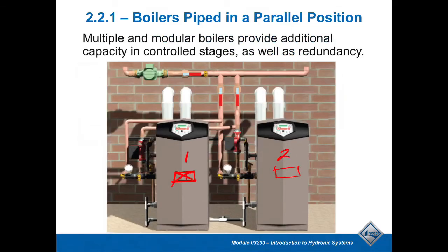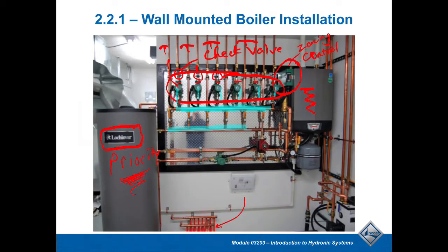So this would most likely be my inlet temperature. I'm just going to identify this one here as that. If I happen to have a return temperature going back into this boiler, I want to keep that at a maximum of approximately 140 degrees Fahrenheit.